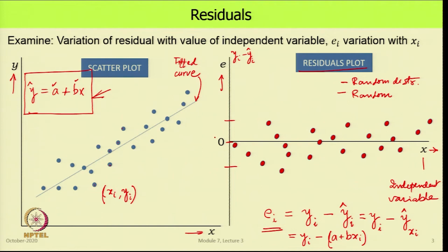Some of these residuals could also be non-dimensionalized and made a percentage, and all good experimental data would always be accompanied by the residuals plot. A very carefully done, very thorough experiment will have residuals in a smaller range, while others may have residuals falling in a larger range.